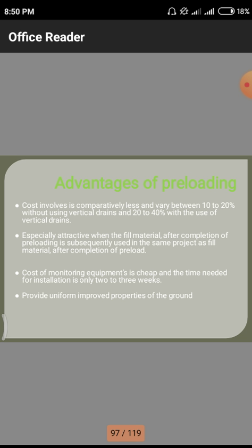That means we are not using any motor vehicles or other mechanical equipment on the site. Normally a huge quantity of filling material is filled on the land itself, so due to the excess load applied on the soil, water drainage and settlement will take place automatically without manpower and machine power, so this is somewhat cheaper than other methods we employ on the fields. It is a cheaper method compared to other methods.